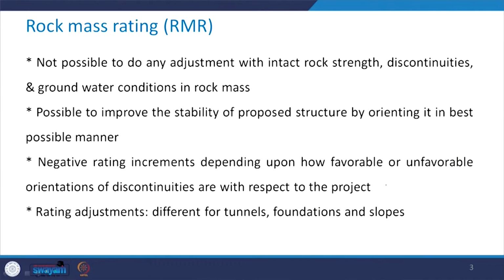Negative rating increments are assigned depending upon how favorable or unfavorable the orientations of discontinuities are with respect to the project, as the adjustment for the orientation of the discontinuities towards the calculation of the final value of rock mass rating.